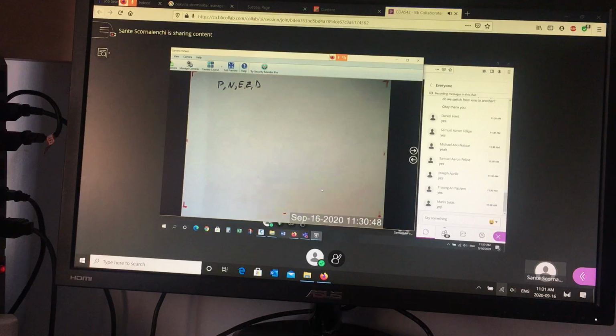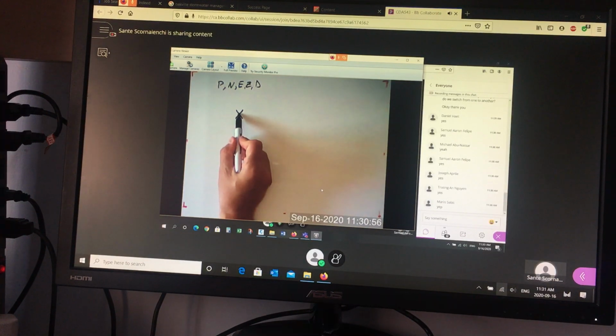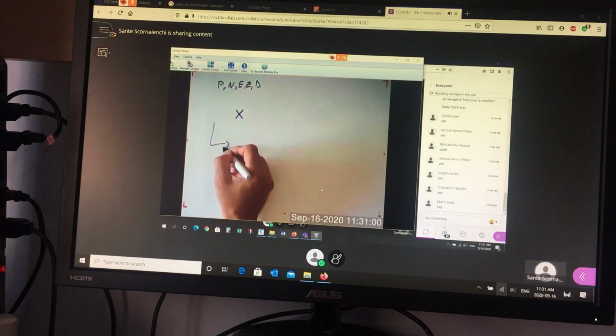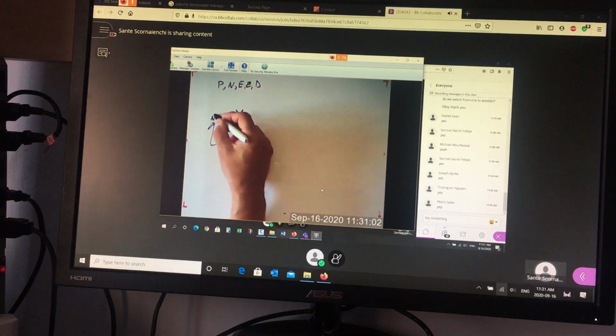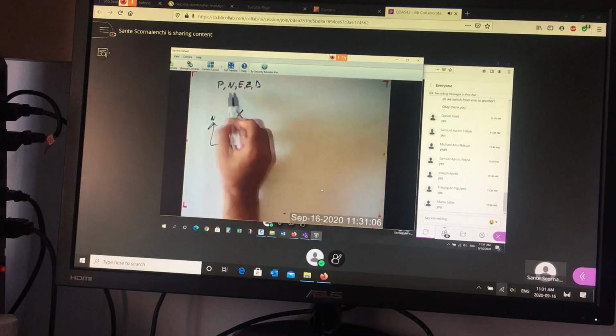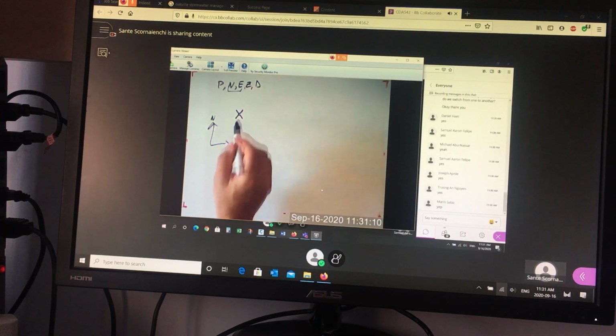The graphical representation of the point has two parts to it. There's the point itself, and the classic look for a point is this mark, this X. And the location of that, the insertion point, is actually the northing and the easting. So that is located spatially wherever the northing and easting is telling you it should be. Okay? So that's what's called the marker.